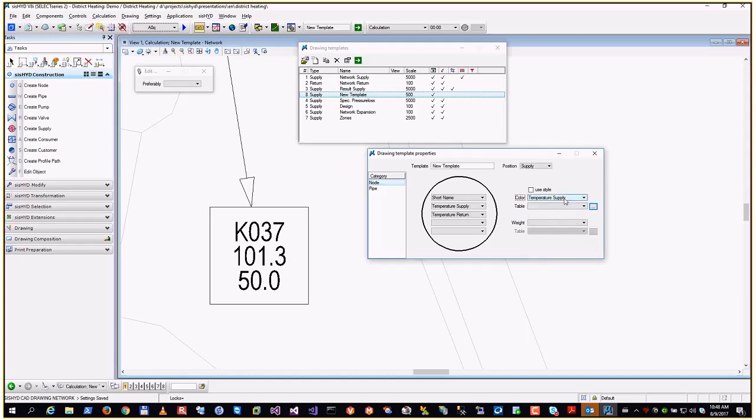And once you pick the temperature, you can drop down the list and see if we already created a color table. There is one, but you are free to, let's pick it first, temperature, and recreate the drawing, and it gets a green color.